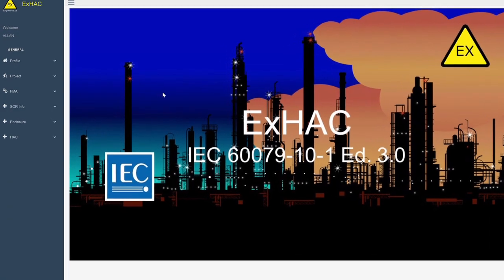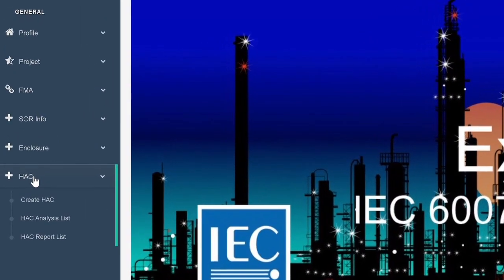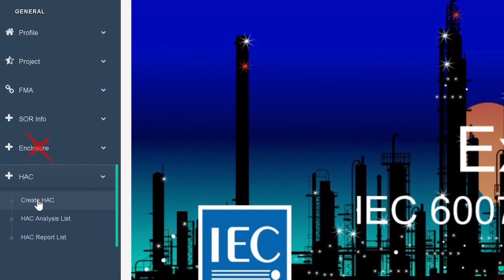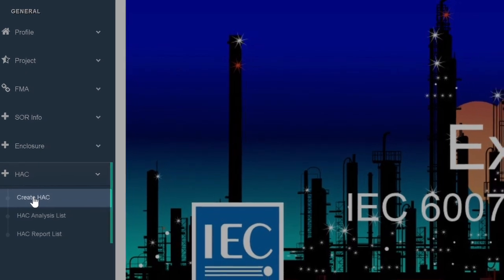Since the pump is located outdoors, in a freely ventilated location, we do not need to create a new enclosure. We can go directly to the HAC analysis. To start the HAC analysis, click Create HAC.